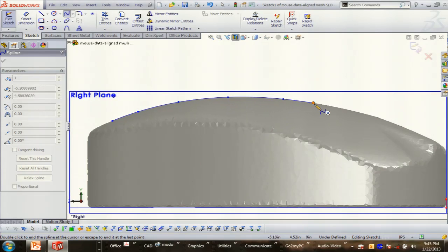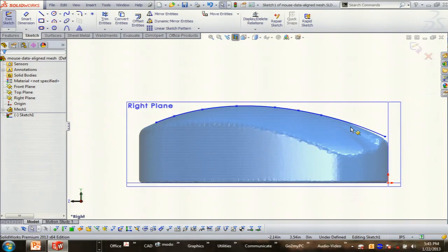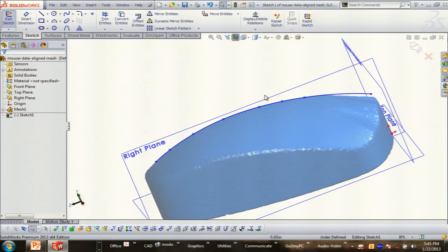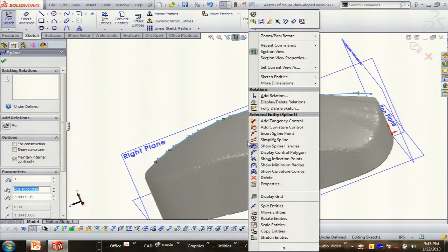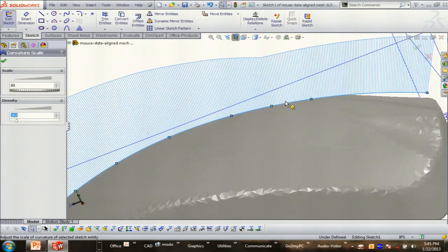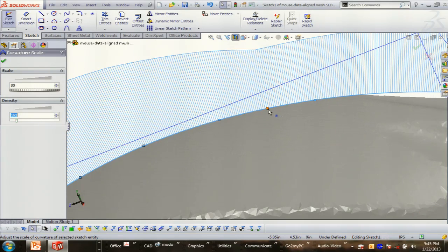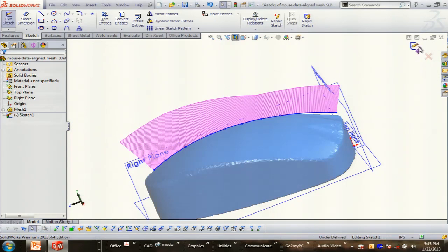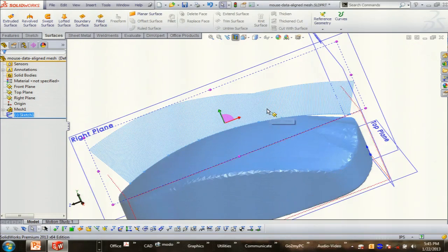I'm snapping to the mesh vertices that are at the intersection of that area. Now, I pulled it away there because there's actually a divot that dives down, and I won't be part of that, okay? But you can see how that works, right? Really nice. If I turn on curvature now, I can see what my curvature's like. I have a little bobble there, so what I can do is eliminate that point and do a little adjustment on the vectors and magnitudes to get a little better curvature flow there. But that's the idea of creating directly against the mesh.